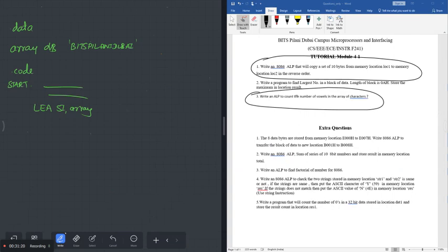If you are using MOV SI, offset of array, I'm not using the MOV instruction here. There is one more instruction equivalent to this, LEA SI, offset of array. Both do the same thing. You can use any one; it is left to you which one you are going to use. So don't get confused between these two, which is very important.